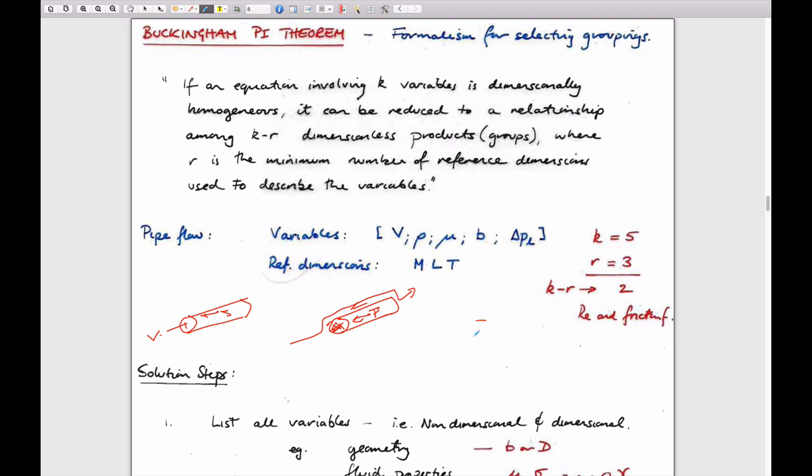And that follows also when we talk about free surface flows. I think we drew these geometries together. And the only difference between pipe flow and free surface flow is that the pipe might be half full. And if the pipe is half full, then pressure cannot be driving it from upstream P1 to P2. Because the pressure would just circumvent the flow by taking the easy circuit and going through the air with low viscosity rather than flying through the water.